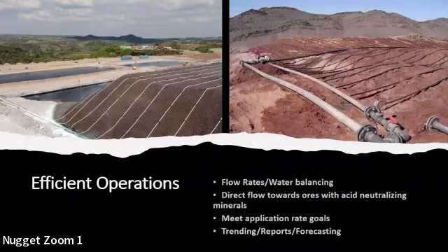The other thing about using this dual wall flex wall system is, one, it minimizes the potential for edge effects, so preferential flow of solution in your measurement cell along the wall, which tends to happen especially if you have coarse particles, gravels, that don't seal up against the wall. By having that flex wall, it pushes in and reduces the potential for edge effects.